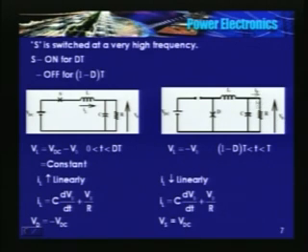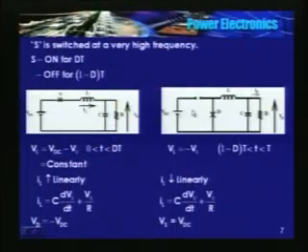As long as this circuit is complete, I naught will continue to flow, and it is supposed to remain constant if the load is constant. So please don't say that the load current is continuous. When I say that current is continuous, it implies that the inductor current IL is continuous.